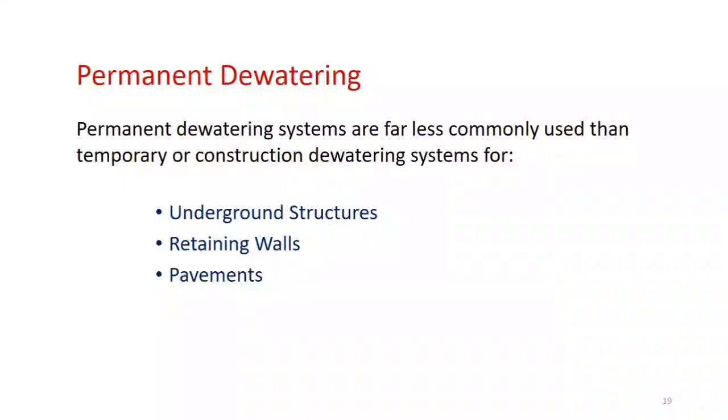Okay? Pavements are very critical structures. You can't allow, in any case, the water level to come in contact with any layer of the pavement, be it base or sub base, because you know that these materials are very sensitive to settlement, cracking, and spalling, and all these issues once there is standing water in pavements.